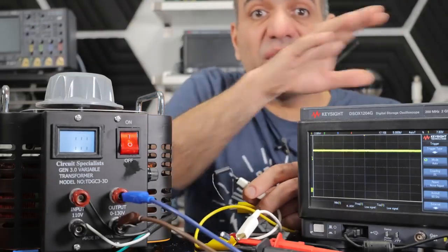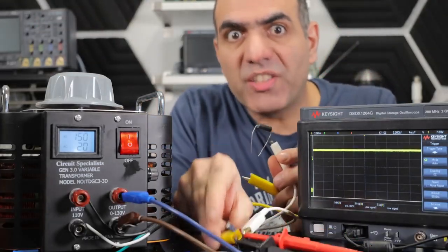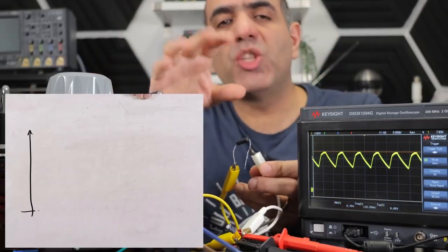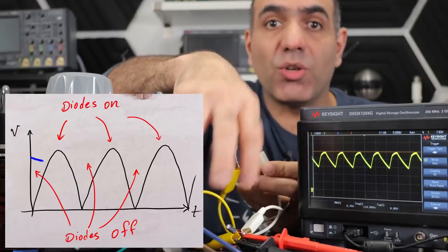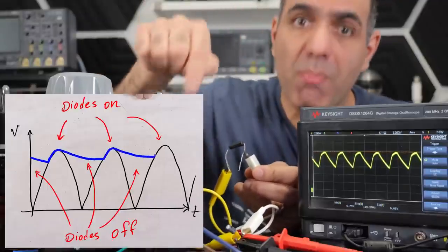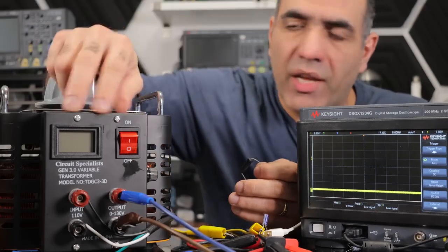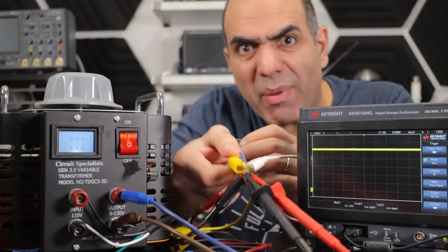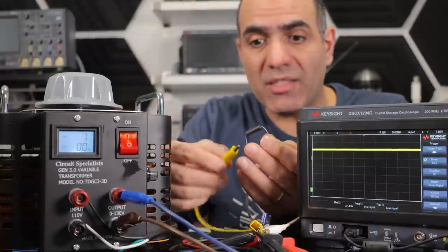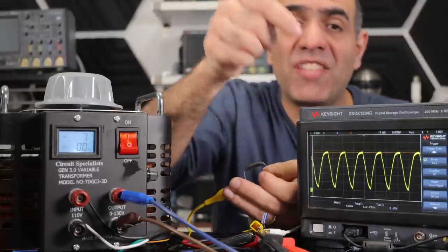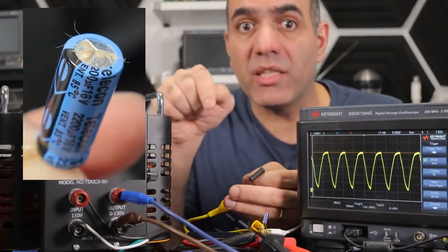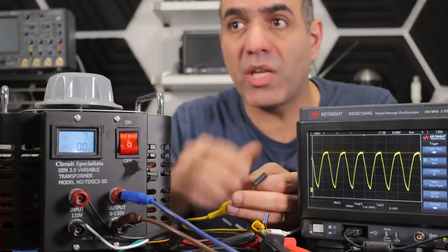So here is the rectified DC voltage with a 100 microfarad capacitor. If I connect a resistor to it as a load, we see it is rippled because during the off periods of the diodes, the capacitor discharges into the resistor trying to keep the voltage up until the next wave of input charges it back up. But if I connect a smaller 10 microfarad capacitor to my circuit, let alone the higher ESR, with the same load, the capacitor discharges so far it can reset circuits constantly. So anytime you see a bulged capacitor, you should replace it with preferably better parameters so they won't degrade the same.